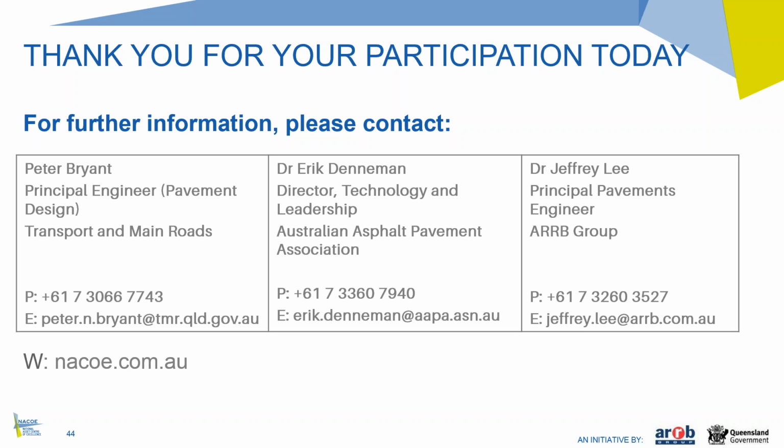Yeah, and I think that's actually a very good point. Historically, mixes in Australia simply have not been optimized for fatigue performance because there was no encouragement to do so in the specifications, and that's really one of the big changes here. It is very well possible to balance rutting and fatigue performance, as the ME2 mix designs show. So I think that's really what we're after here: come up with real performance-based design of asphalt mixes that will lead to superior products, and that encourages the use of those in our pavement design system.